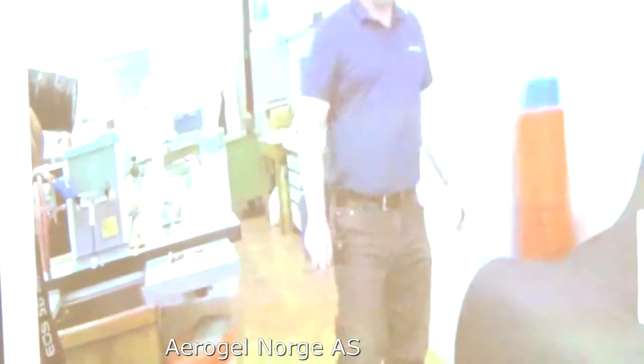The test report from the EMPA Braunschweig is in Germany. They measured the system to the European standard 13501, and it says it's A2S1D0, that means A2 non-combustible, no smoke evolution and no combustible dripping.